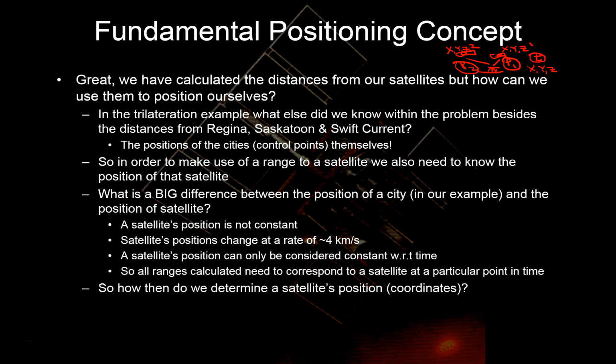So how then do we determine the satellite's positions? How do I gain information about X, Y, Z and X, Y, Z? And again, we talked about this when we talked about the control segment, right? One of their responsibilities was, okay, they monitor all the information coming down, but they also send up that ephemeris information. So the information goes up to the satellite, and the satellite just grabs it and starts sending it back down. So the satellite itself is telling the receiver exactly where it is.